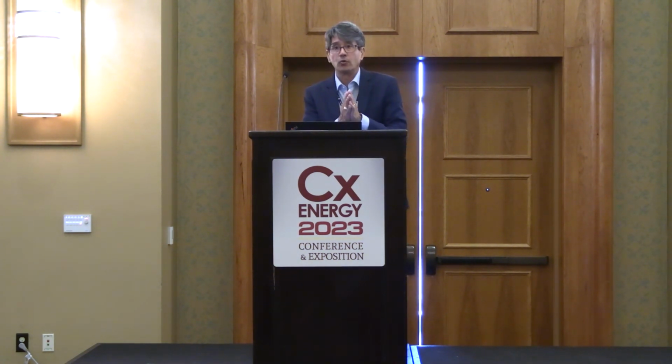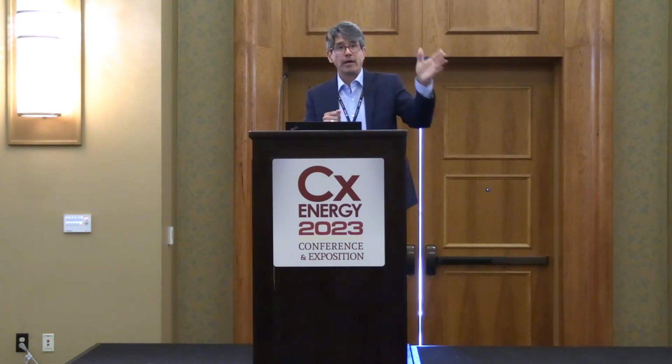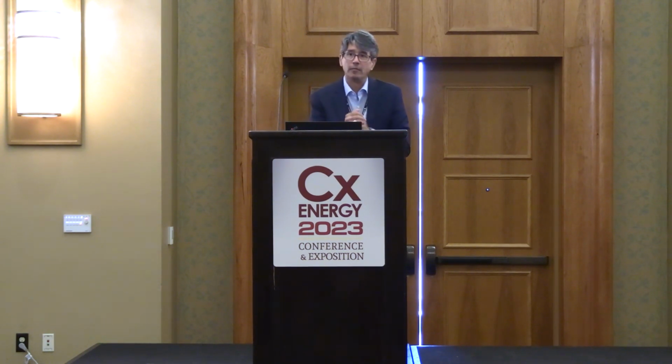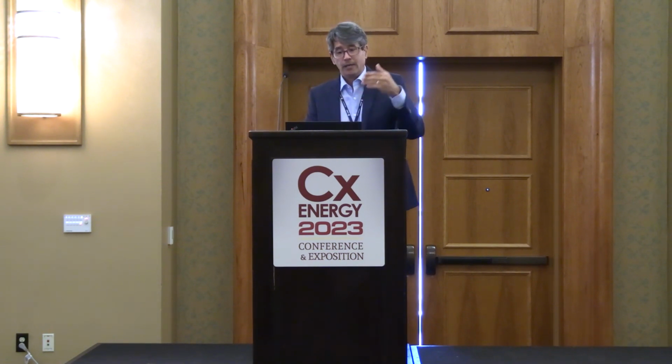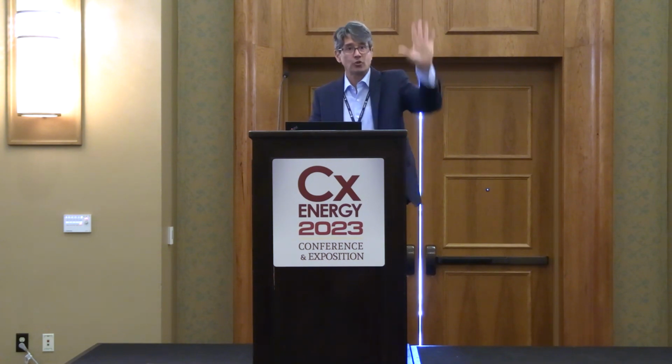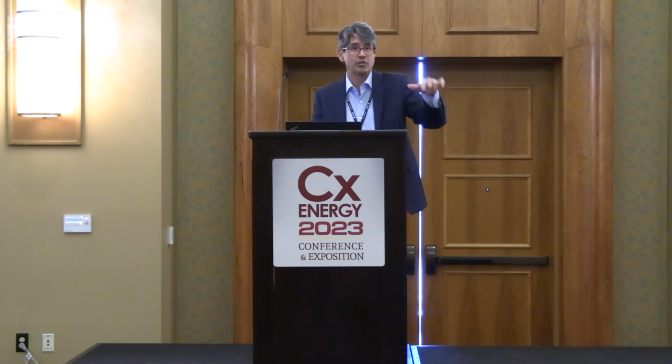Unit vents, we see a lot in our schools getting remodeled. They're putting a lot of unit vents in. And you get a schedule, 35 for minimum outdoor CFM, 130 for max. There's no way to accurately measure those. And getting people to understand that, and they went to the whole trouble of specifying this, saying, here's what I need. Unit vents, if that unit's installed in the same configuration, no added ductwork, the louver that they put on there in the factory and sold with it is the louver that's used on it. You can use their manufacturer published data, and you're going to have to use that to set the positions to the damper.